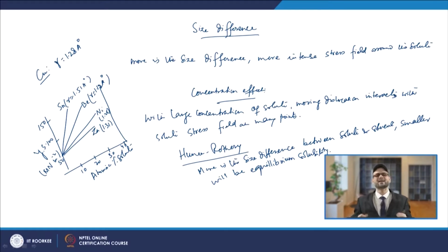Another way we follow is that we go to a higher temperature. We normally try to get a supersaturated, metastable solid solution, so you go to the higher temperature and then quench it, you cool it fast, so that you can trap the larger concentration of the solute at room temperature, which otherwise is not possible. That is how we also try to have strengthening, by going into the zone where the solubility is more, and then cooling it fast, or quenching it.